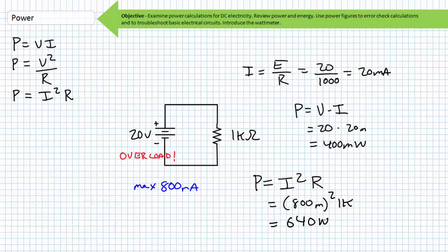You want more proof something is awry? If the 1 kilo ohm resistor was really drawing 800 milliamperes, we can use Ohm's Law to figure out how much voltage would be necessary to supply this current. Voltage is equal to current times resistance. 800 milliamperes times 1 kilo ohm yields 800 volts. Something is terribly wrong and nothing makes sense.